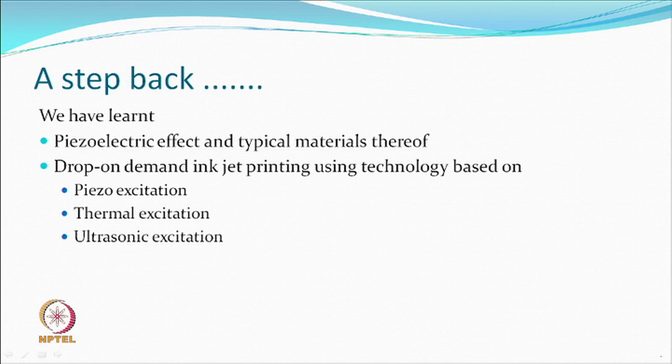Drop on demand technology also has thermal excitation, which means a bubble is created by heating, and the heaters could be anywhere on the top, on the bottom, on the side.